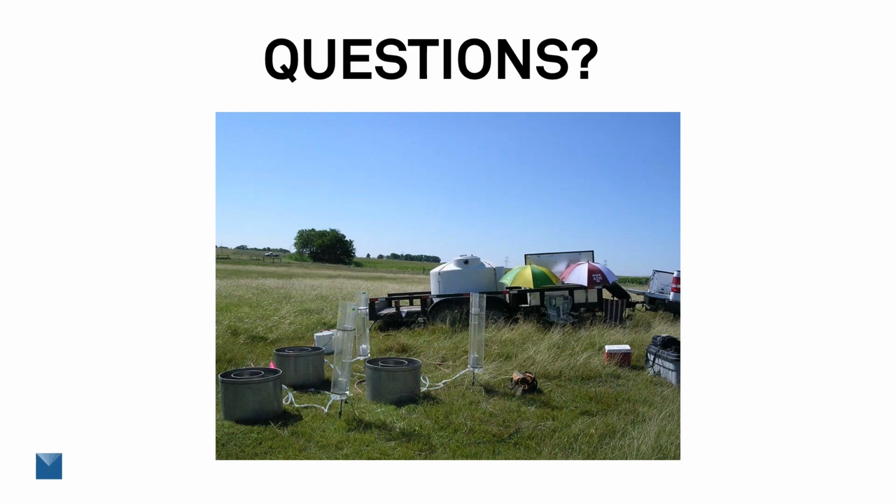All right, last question. How would you make saturated hydraulic conductivity measurements in soils that have cracks? Yes, this is something I spent a lot of time doing, because a lot of my research was in vertisols, which are highly expansive soils in Texas. We often had to deal with cracking soils, almost to the point where we made a measurement on a site where we didn't know there was a crack, and we went through an entire 500-gallon water tank on that one measurement.